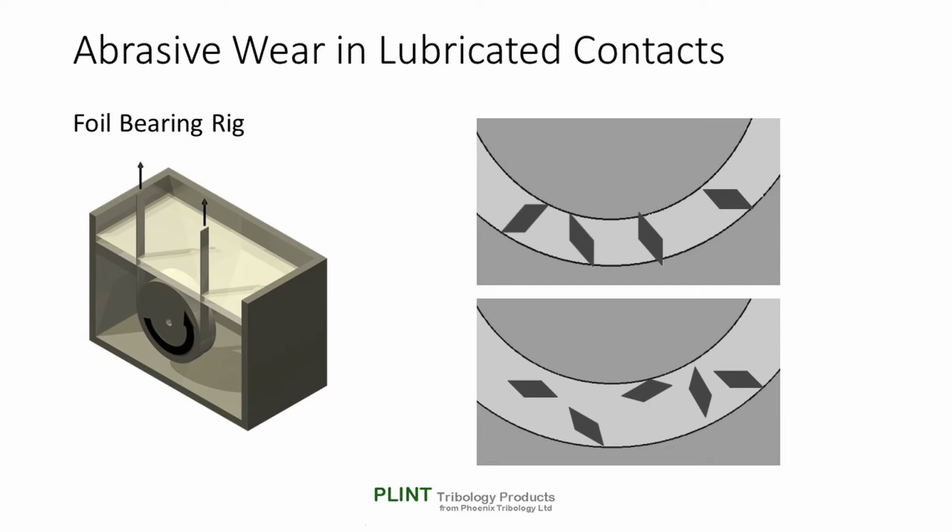For surfaces of similar hardness, grooving wear may occur on both surfaces of the tribo contact. For surfaces of different hardness, there are two possible mechanisms that may not be mutually exclusive. If the surface roughness of the harder surface is sufficiently large, particles may become trapped by asperities and be dragged through the contact, producing grooving or micro-machining wear of the softer surface.